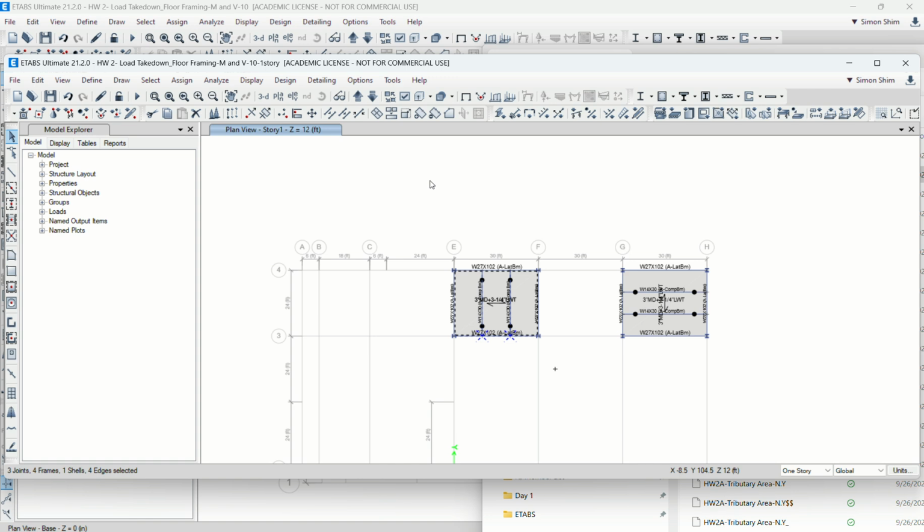Divide by 12 to make it feet, times concrete 115 pcf, so this is roughly 45 psf, including metal deck weight. So we can calculate the equivalent weight of the metal deck slab by converting to a flat equivalent concrete thickness, and we should be able to calculate the uniform load, right?